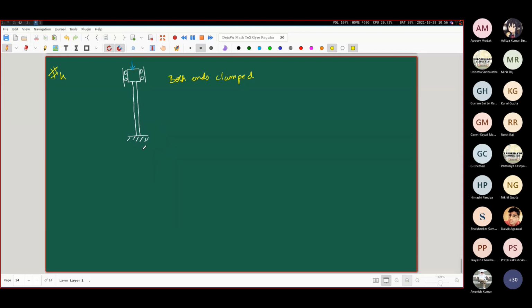What you have to do is at x equal to 0, impose the condition that y equal to 0 and dy/dx equal to 0. And at x equal to L, similar conditions, y equal to 0 and dy/dx equal to 0. So please try to do this and try to get a condition. Mind you, in the last few steps, you have to unleash your JEE level algebraic manipulation skills to get a neat and clean solution. But it's quite fun to do. I'll of course show this myself also, but try to do this on your own.